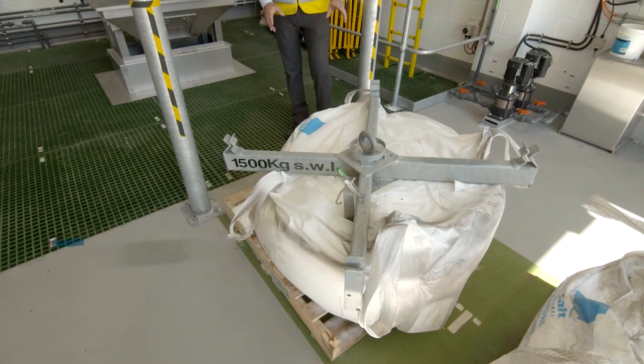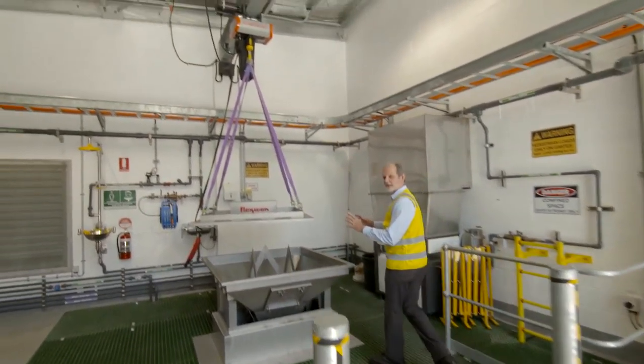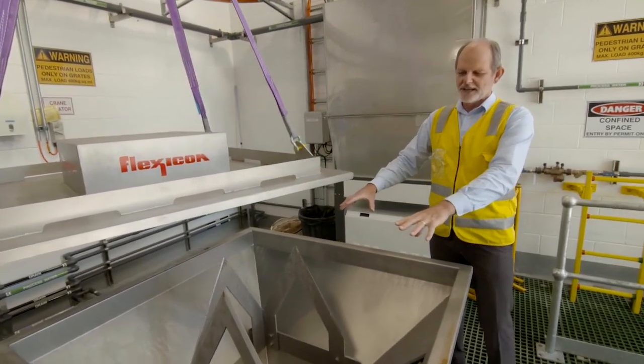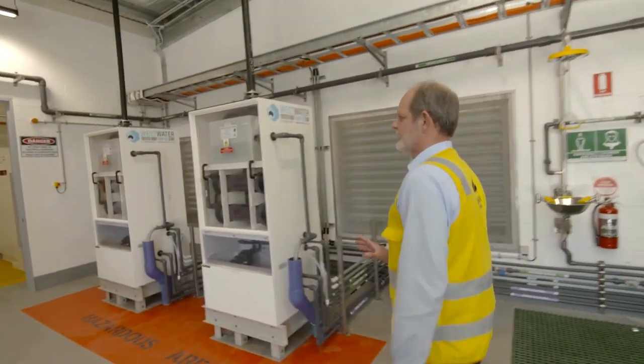So this is where our process starts. We bring in bagged ultra-pure salt. That salt is lifted up in the bulk bags over to our brine tank. The bags are lowered down, the splitters open the bag and the salt drops through into the brine tank. The concentrated brine is then transferred over to our electrolysers.